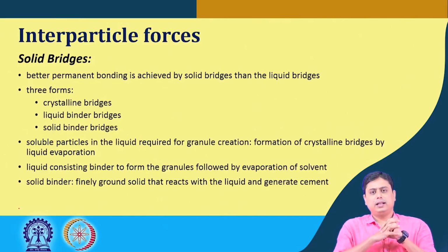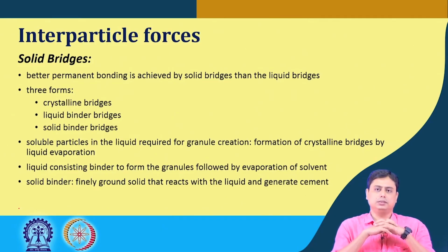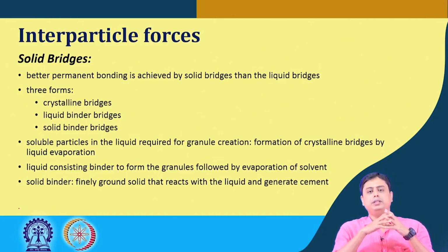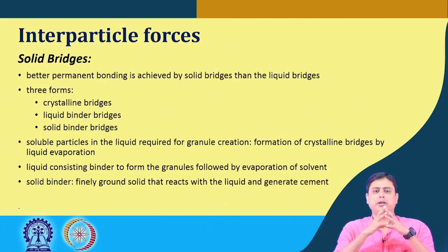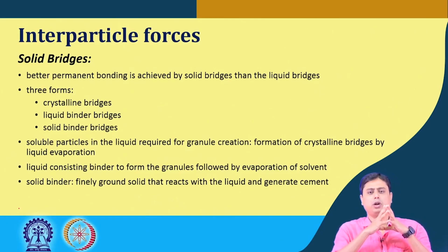The other force is the solid bridges. Liquid bridges we have discussed in the different states of pendular, capillary, funicular and droplet states. Now, liquid bridges are not actually the ultimate stage of product generation. Better permanent bonding can be achieved by solid bridges than by liquid bridges. It typically has 3 forms.